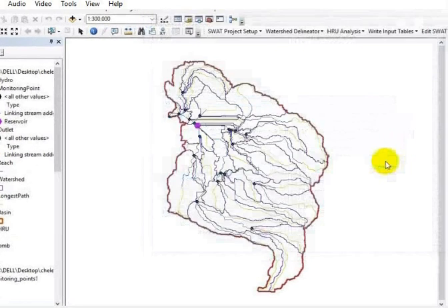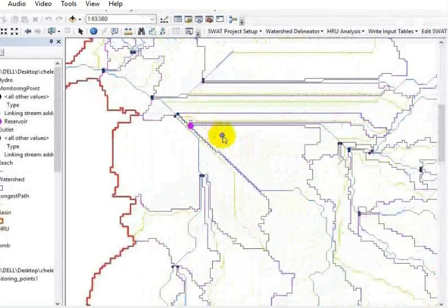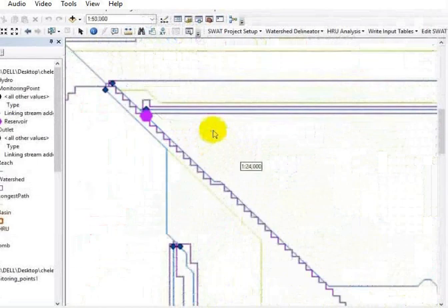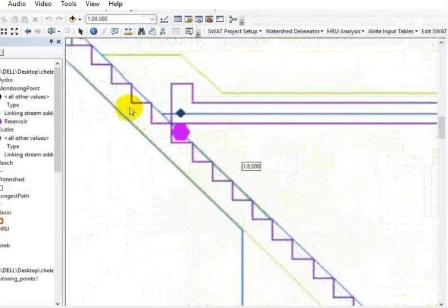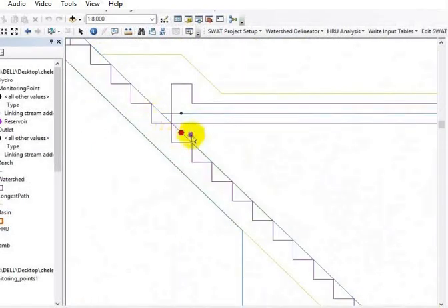So to create those reservoirs, I will follow this procedure and go to that specific sub-basin, and I will click the outlet point for the reservoir, lake or pond. In my case, I have previously added those reservoirs, so simply by clicking this red button at my reservoir area, I will create the reservoir.